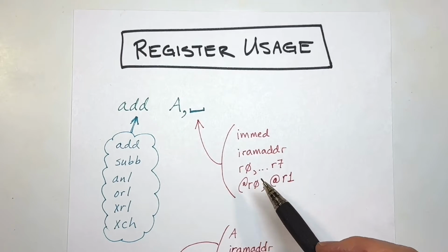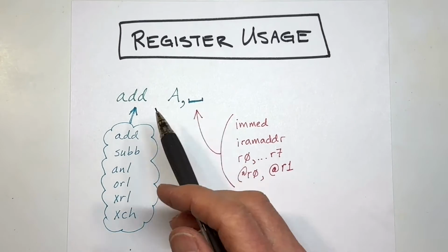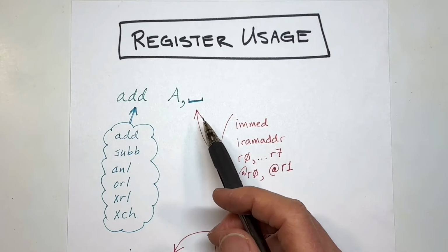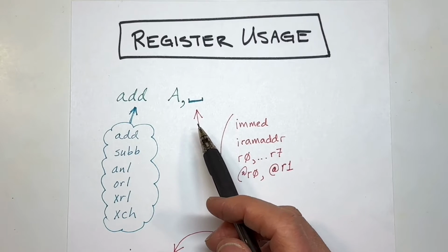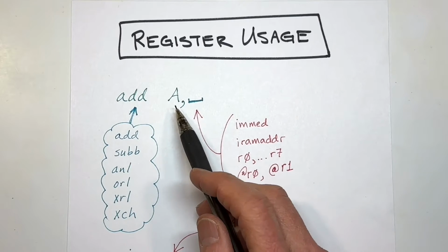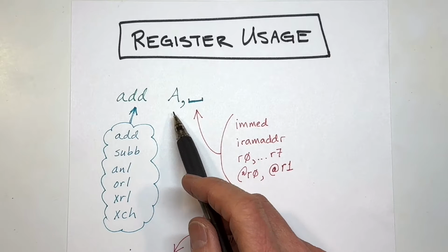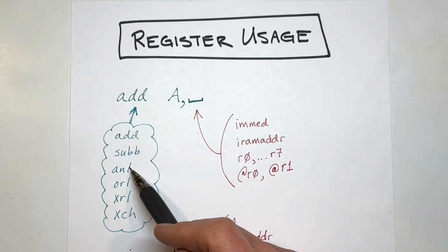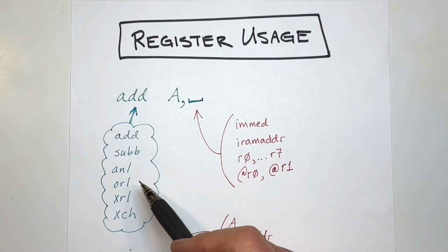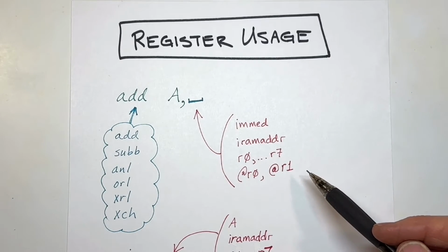The instruction set for the 8051 is not very regular, so if you're wondering whether there's an instruction that can take operands in a certain way, then you basically need to consult the instructions list and try to determine that. For example, we saw previously an example of the AND instruction where the result is placed back in memory using direct addressing. And that's available for the AND instruction, but not the ADD instruction. There's also an add with carry operation with a different set of operands.